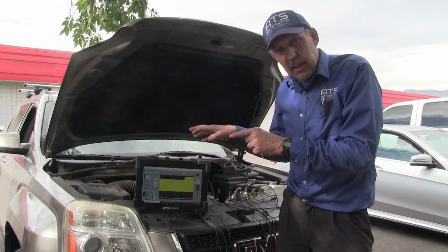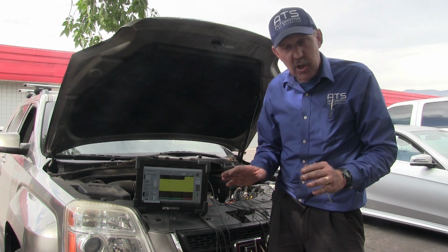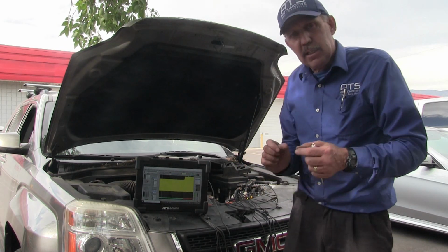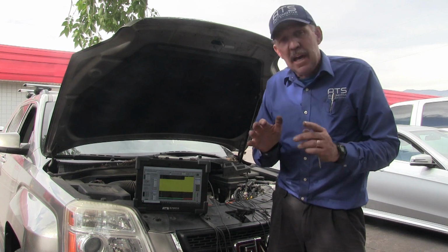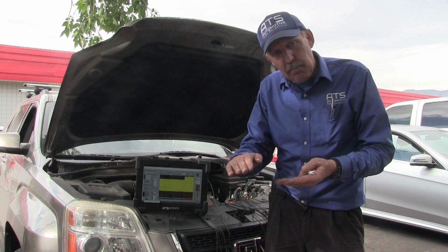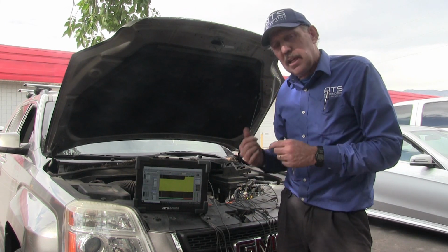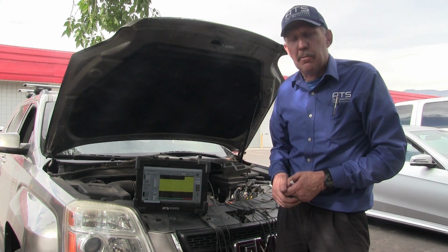First we disconnected the O2 sensor. There was no change. That means it's not loading. Then I disconnected the ECU circuit and it popped up. If it would have stayed pulled down, that means the problem is in the harness. Now we know the problem is in the ECM. This ECM is going to need to be replaced.